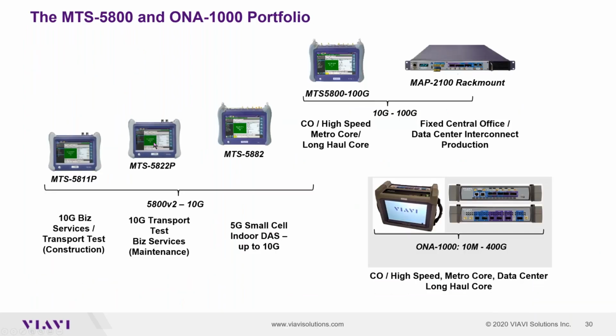Okay, about the portfolio from Viavi. This is the only portfolio in the transport testing area. And if it's backhaul, easily you have 100 gigs. So this is our MTS 5800, 100 gig. It supports up to 2 completely independent 100 gig ports, with OTN even 2 independent 112 gig ports. You can have the same fixed installed as a rack mount unit.